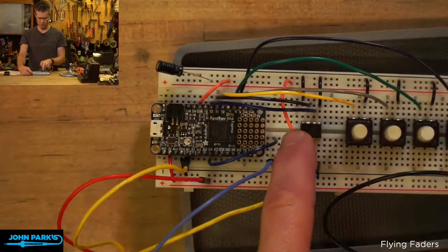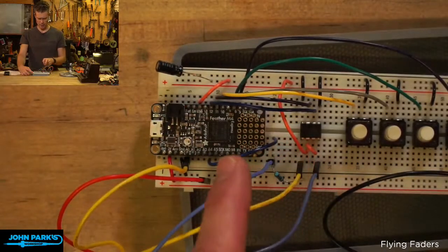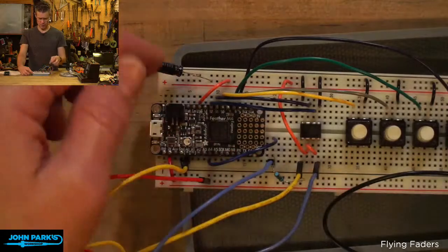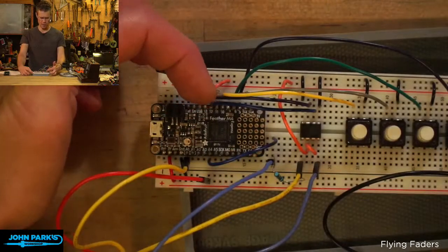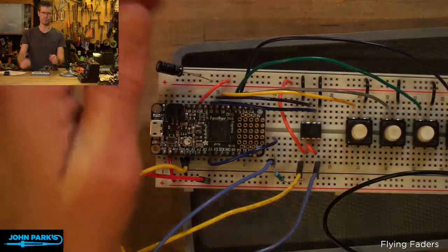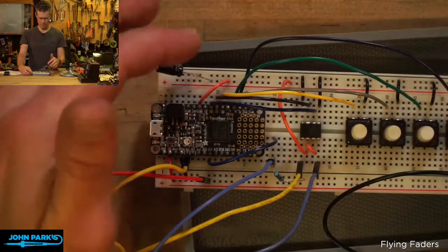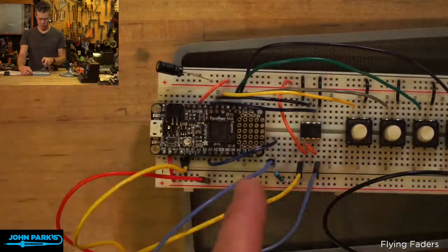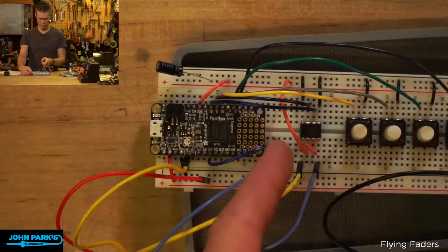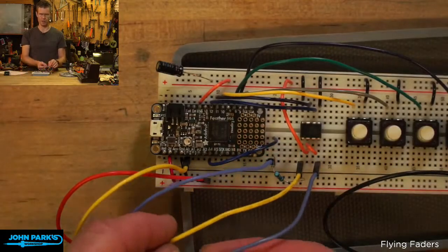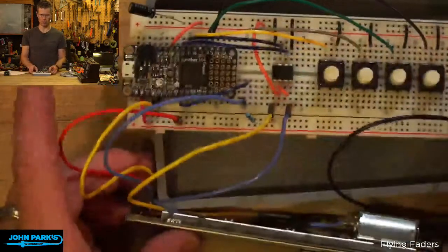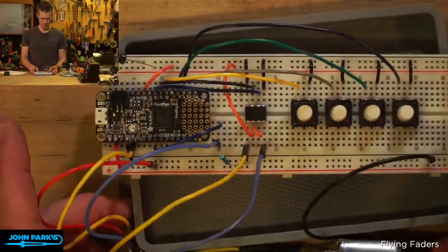The little motor driver chip there, the H-bridge, then has a couple of connections for PWM on the microcontroller, so we can send it in one direction or the other using PWM. And then the rest of the connections up here to ground. We have 2 pins that get the USB 5 volts, and then the output to the motor. That's what that one is right there.